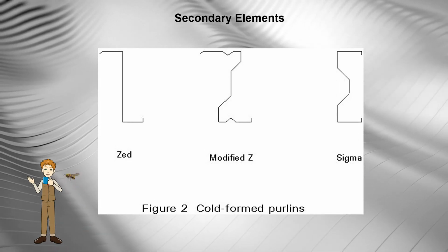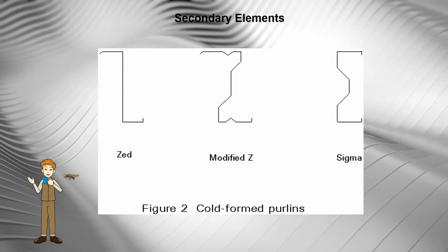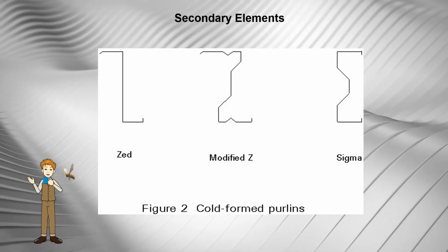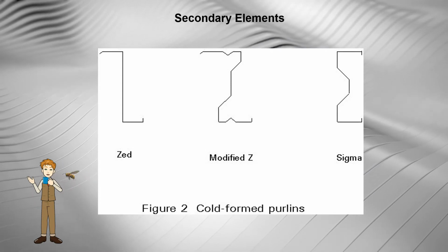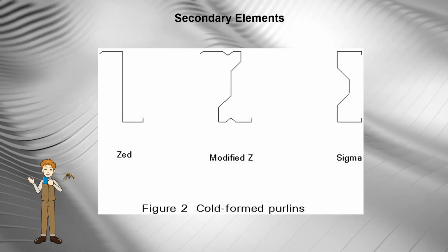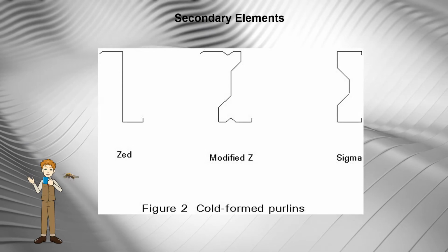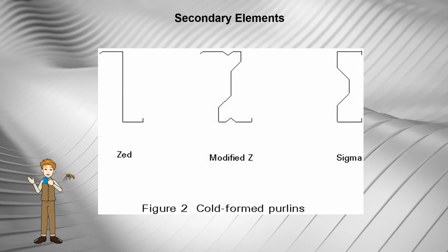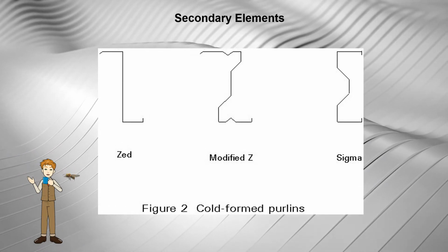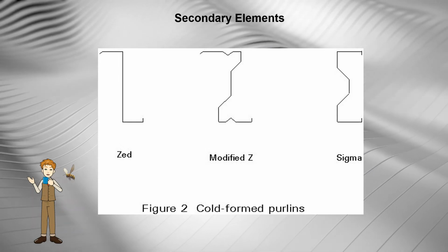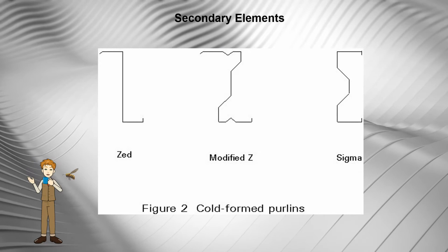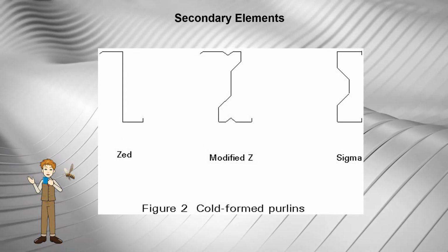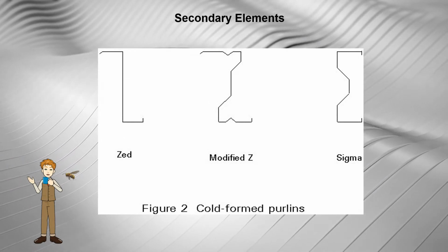Spans are commonly 5 to 8 meters, but longer spans up to 12 meters can be achieved. It is also traditional to use hot rolled sections as I or C shapes, not so sensitive to the effect of local instability. The center-to-center distance of the portal frames is then reduced, in general, to 5 or 6 meters.